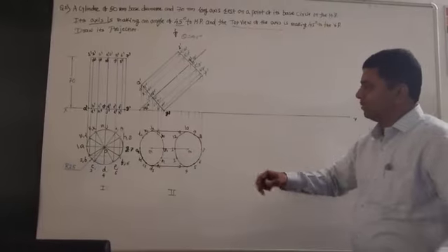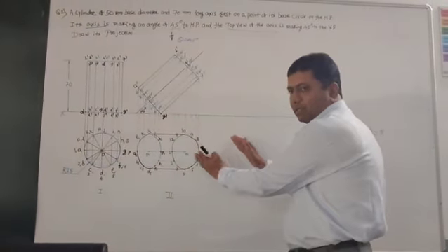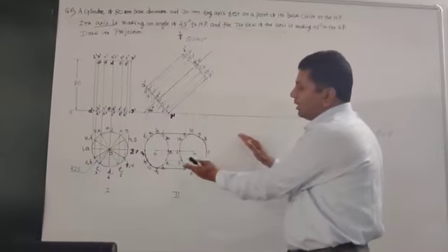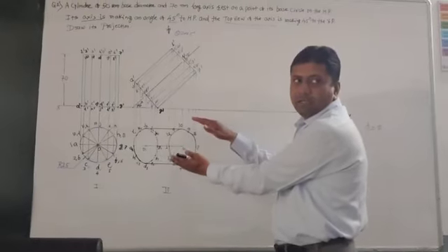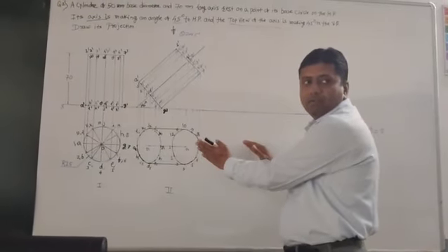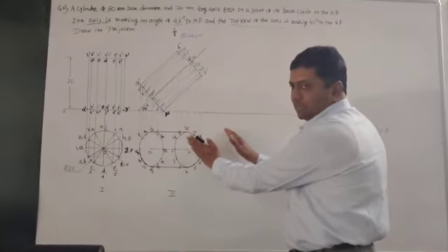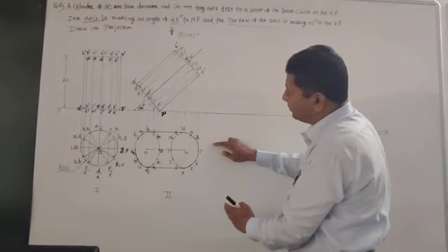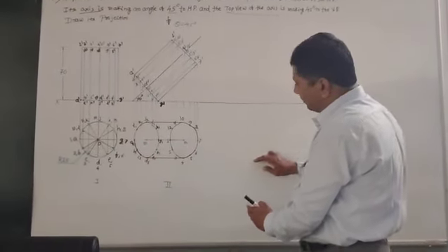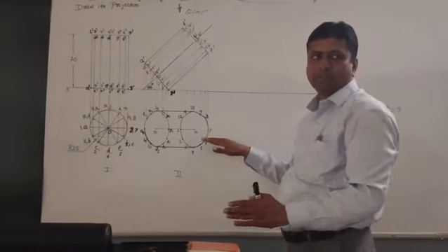So we will do it. That means what we are doing, this top view, we are rotating along the axis O1, O1 at how many degrees? 45 degrees. Means I am rotating this top view like this. Understood? When I am rotating the top view like this, this portion will be here and this portion will be here. Correct? So I will draw it, okay, step by step.